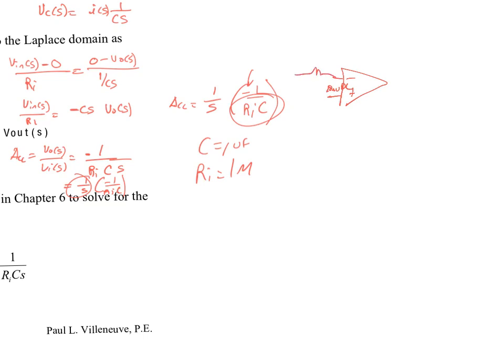Well, oops. Kind of a problem if it's an integrator, right? Because you're always going to have a non-zero value here, which means you're always going to be feeding electrons into there until it saturates, correct? So this is an integrator, but it doesn't work for real-world op amps because it's always going to have some DC offset that's going to feed that capacitor. So the question is, how do you actually fix that problem? How do you make it an integrator that works?